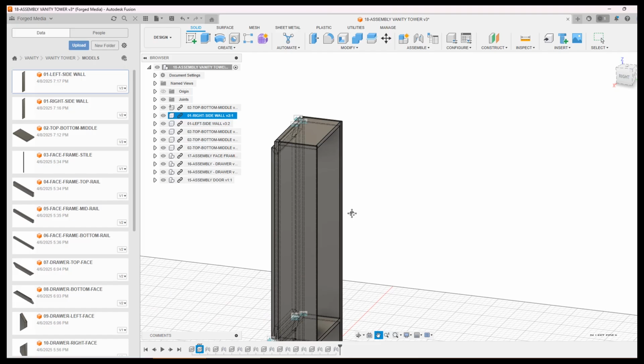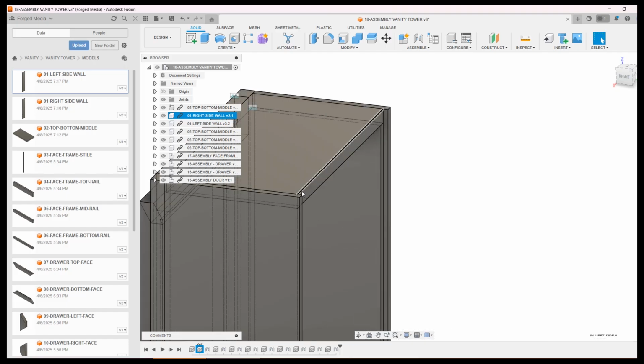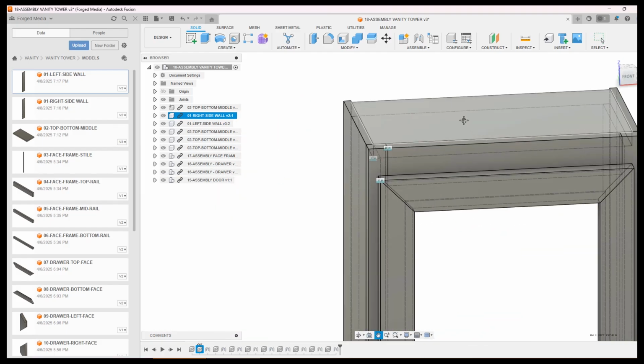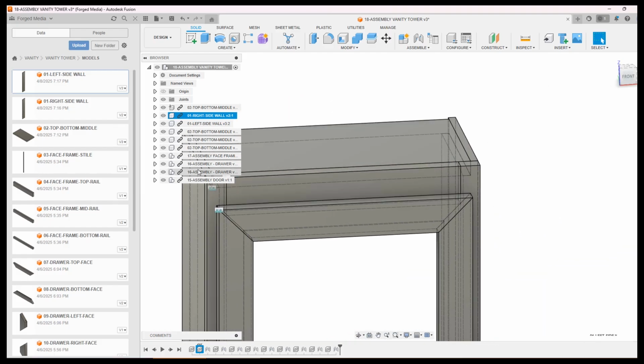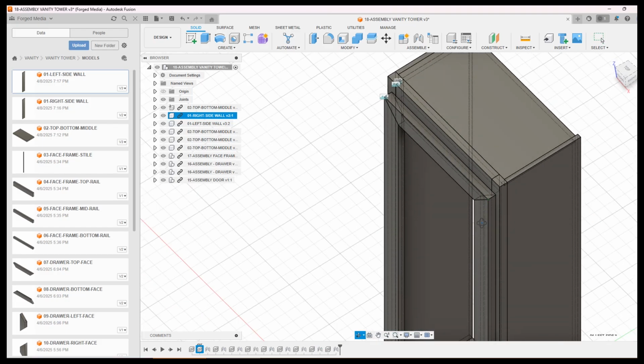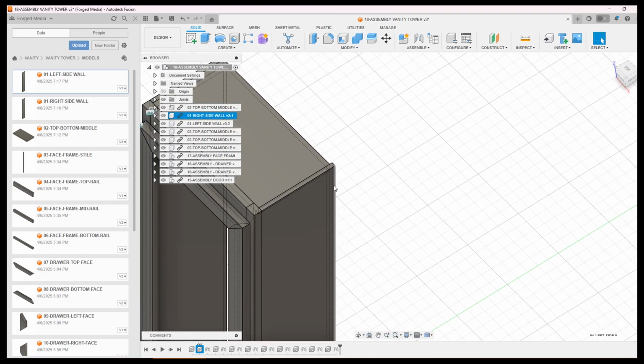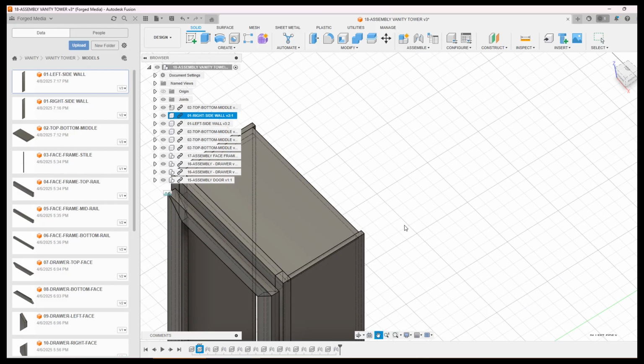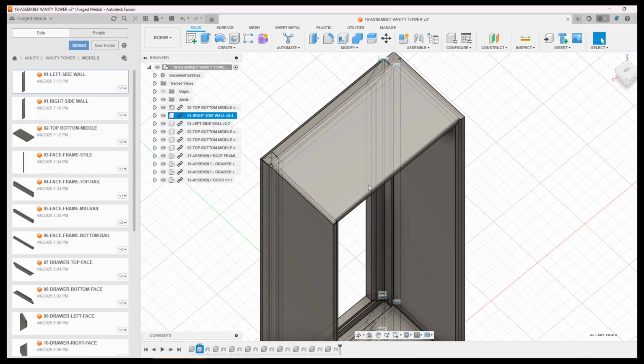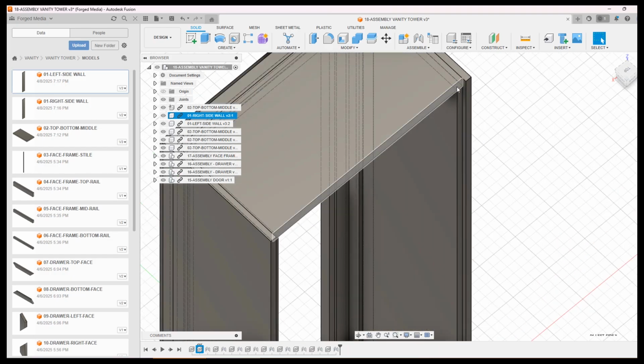Now, I'm not worried about the top being open here because that panel is going to go straight here, and I'm going to wrap the top of this with a piece of trim, so you're not going to see that at all. It's going to be much easier to just make rabbets on these two panels versus having a part up here where I trim out that little edge to cover that. But if this was going to be seen, I would do that, but in this case we don't need to.